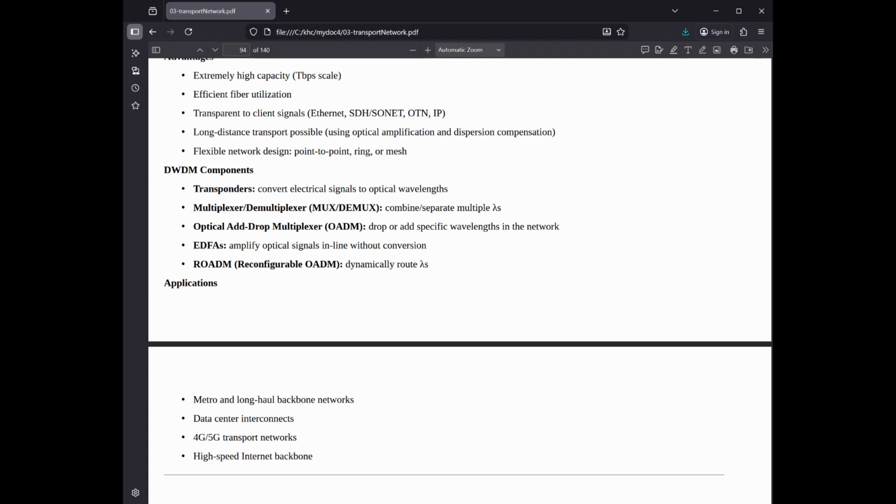Component summary table. Transponder, OTU/OEO, Passport Control: standardizes signals to specific colors. Multiplexer, MUX, Highway on-ramp: merges multiple colors into one fiber. Amplifier, EDFA, Fuel Station: boosts signal strength for long hauls. Add/drop MUX, ROADM, Exit ramp: selectively picks signals for local use. Demultiplexer, DMUX, Highway off-ramp.